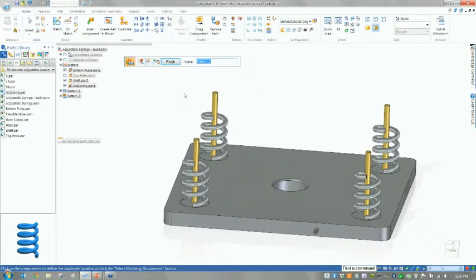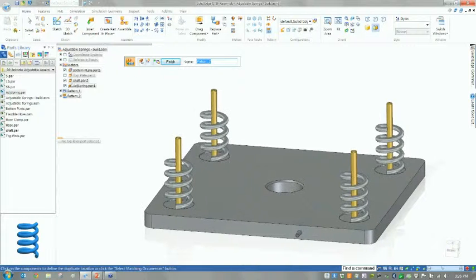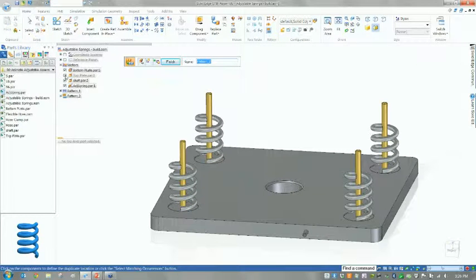Wherever that post is, that post gets a spring. It doesn't matter if it's upside down, if it's on the outside edge, or if it's going around in a figure 8 pattern. Wherever that post is, that's where the spring goes. That's called duplicate component. It allows me to attach, basically, one set, and then everywhere this goes, it just finishes out the set. So we'll have something like that.